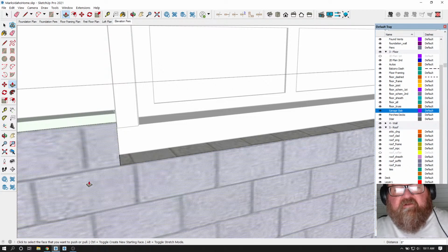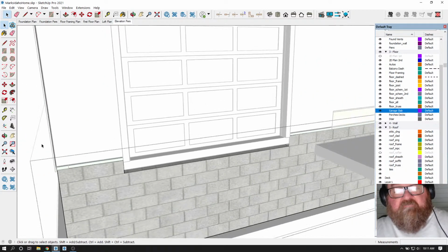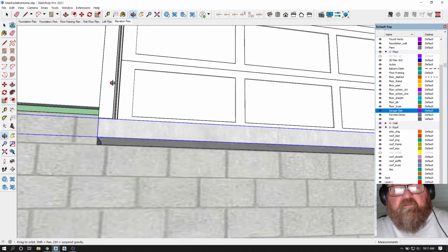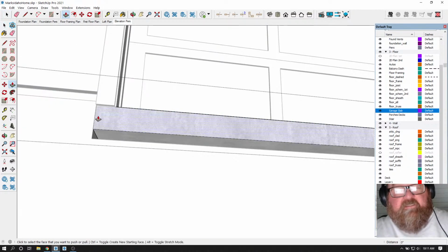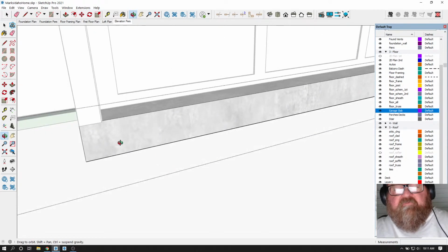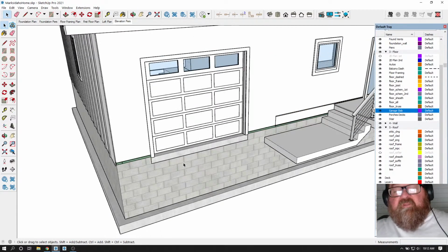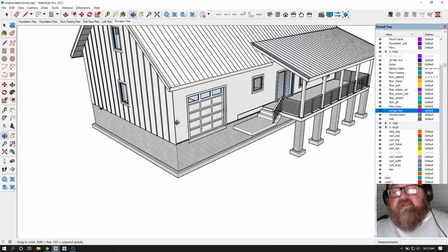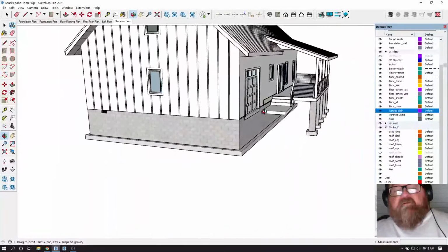So they'll just leave out a course of block, and then your slab, the edge of it, not the whole thing, will be turned down right at the edge to make it thicker. Just on the edge for about a foot back, maybe 8 inches to a foot back. And I'm not showing the ground. I gotta fix the grade. All this is below ground out here.